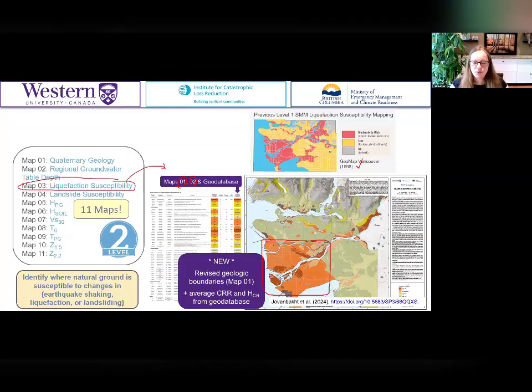It's also still pretty high susceptibility to liquefaction, yes. But we added columns that explain what we know about the subsurface ground conditions in each of these geologic units. We try to summarize how resistive the soil is for those geologic units, and therefore confirm what the liquefaction susceptibility should be. So it's a slightly more sophisticated level 2 seismic microzonation map product.